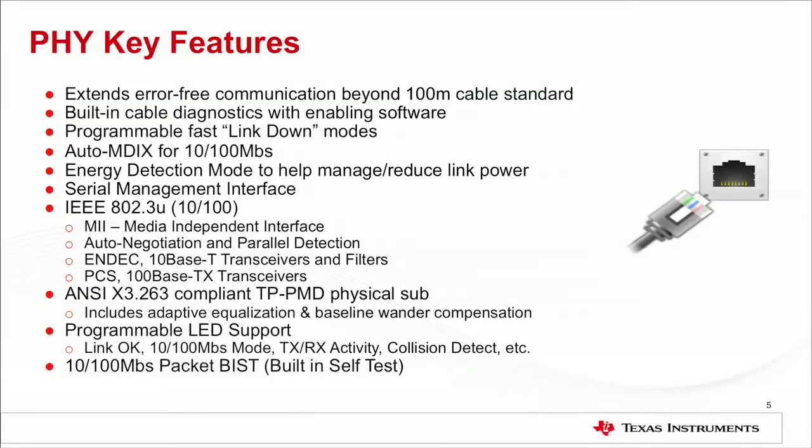I want to take a minute to review the key features of the PHY now. The integrated PHY allows for error-free Ethernet performance beyond 100 meters. Features such as built-in cable diagnostics and fast link down modes are supported. PHY registers can be programmed by MAC using serial management interface. The serial management interface is compatible with IEEE 802.3-2002 standard and includes an MDC management clock input and management MDIO data pin to the PHY.